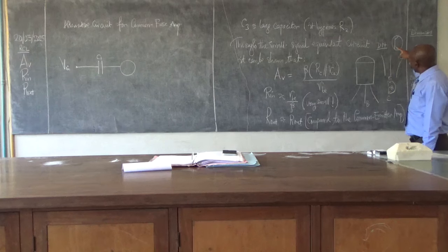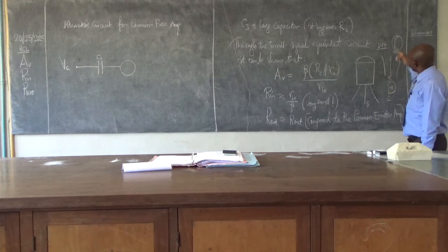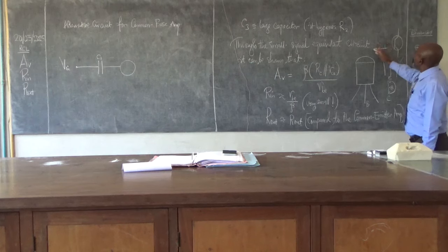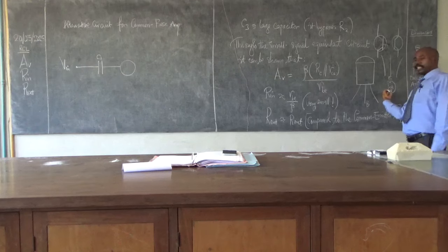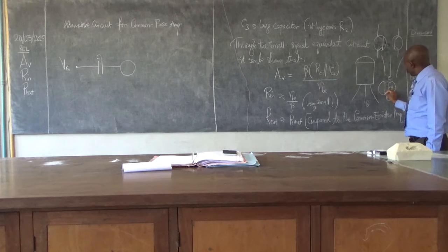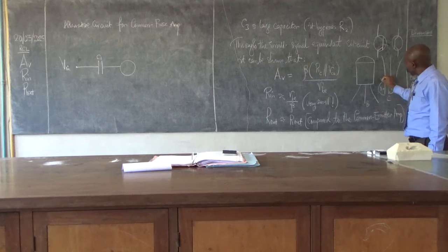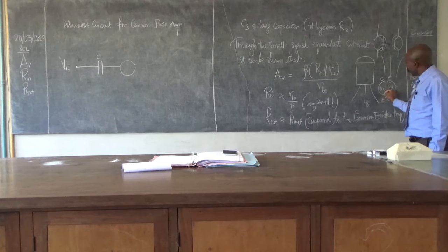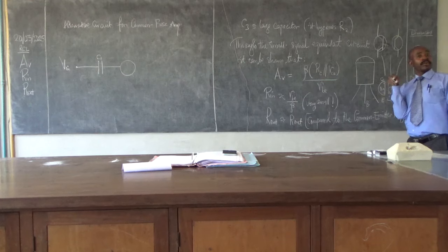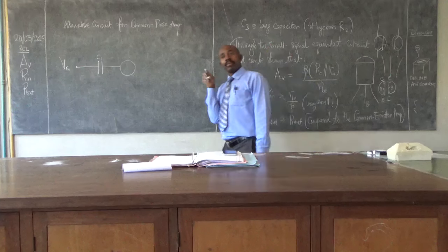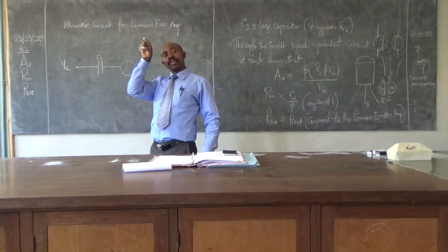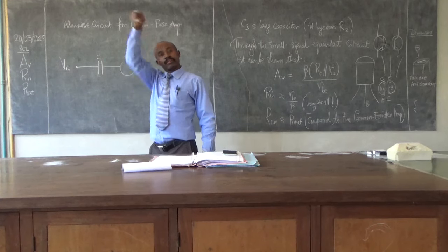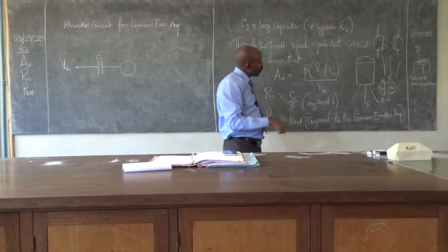So if this flat part here is this line here which we normally draw, and the other transistor is like this, that means that when you plug it facing this way, then base remains here, but now this one becomes collector and this one becomes emitter. So when you are connecting the legs, you must know this, and look for the emitter up there, and then the collector will be